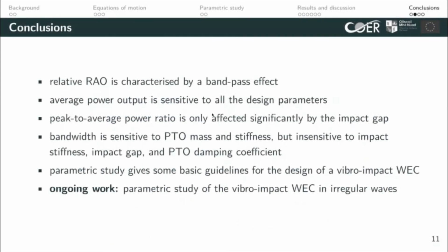Based on the simulation, here we can summarize the study. The relative RAO is characterized by a bandpass filter no matter how we design the variable impact parameters. The average power output is sensitive to all the design parameters, and the peak-to-average power ratio is only affected significantly by the impact gap. The bandwidth and the natural frequency are sensitive to the PTO mass and stiffness, but insensitive to the impact stiffness, impact gap, and the PTO damping coefficient.